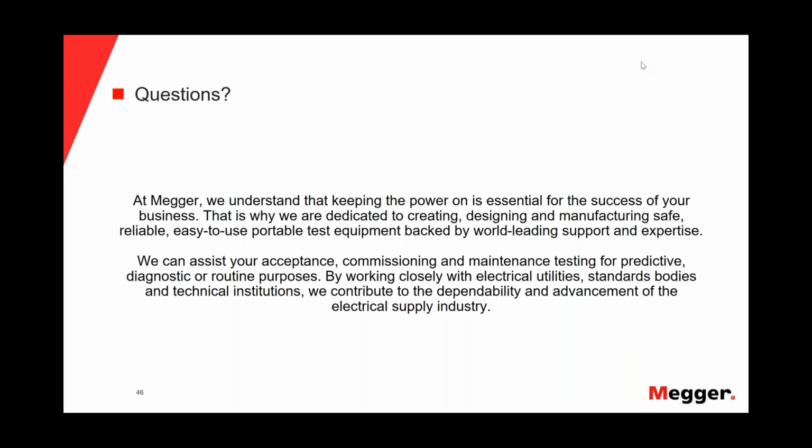Thank you, Sergio. Henning, would you agree that we should approach factory test results after installation under ideal conditions so that we can use factory test values as references? This brings back an old question, and I think the common opinion on this is you cannot reproduce factory test results, which are taken in a noise-free Faraday cage environment, and expect to see the same in the field, because in the field you don't have this shielding.